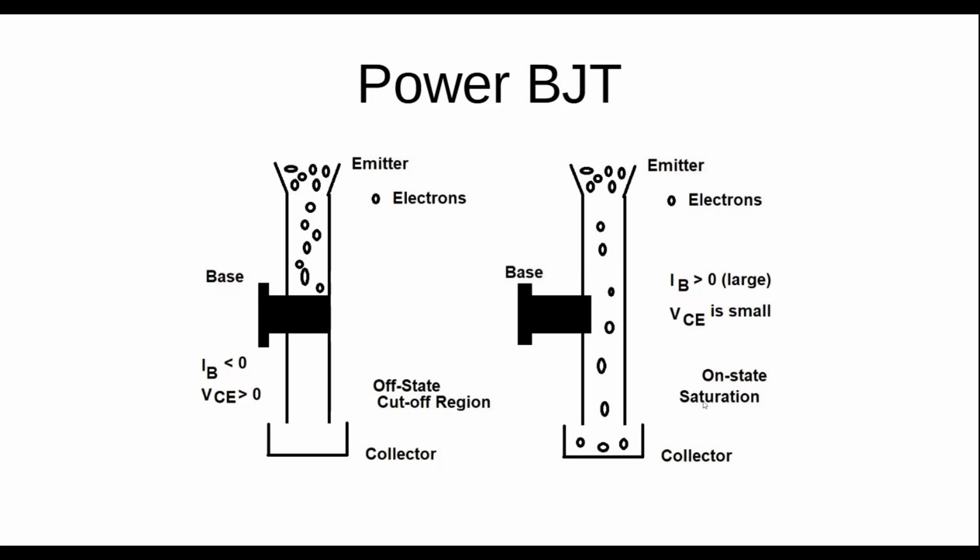So make sure you have a heat sink, especially when you're working with these power devices. All of them, even the diodes, dissipate power. Not as much as in some other cases, but there's always power dissipation because you're dealing with large amounts of current.